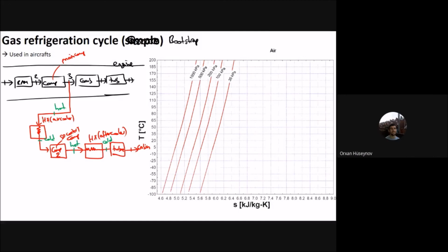So it means that at this stage, from hot to cold, I need a fluid that is cold and becomes hot. That is again supplied by this ram air here. And this one is for the exit to atmosphere. At entrance it is cold, and at outlet it is hot. And I will supply one more ram air here. I will take one more ram air from that line, and it will go to the next exchanger.